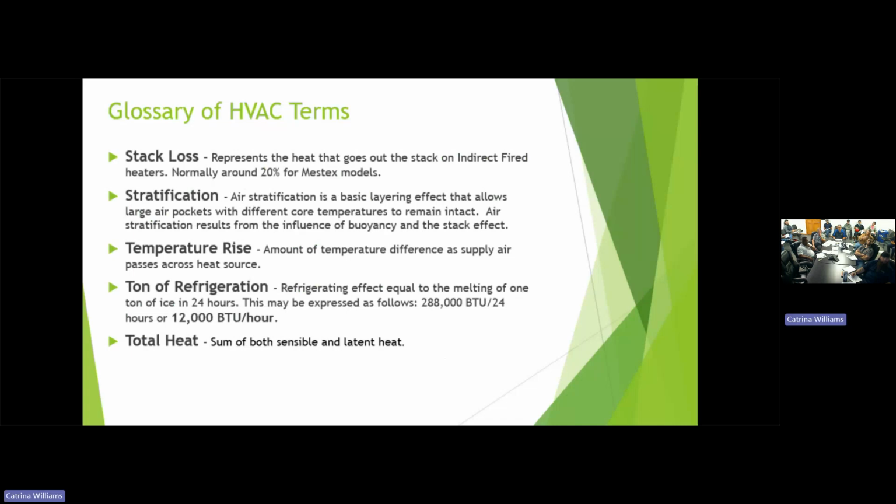I know, for example, the one across the street, we have a heater in there. They put heat in that space, be that a direct fired unit on the side, and they keep the space warm. It might be 65 degrees at the floor level where the workers are, but it's like 100 degrees at the ceiling. I know from experience that they go over there about 30 feet away and turn on that air turnover unit. No cooling on it. They just get the air moving.